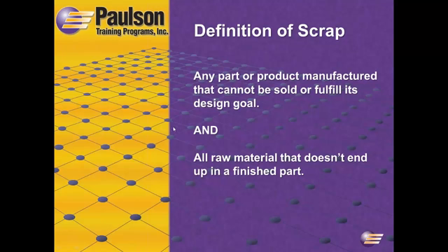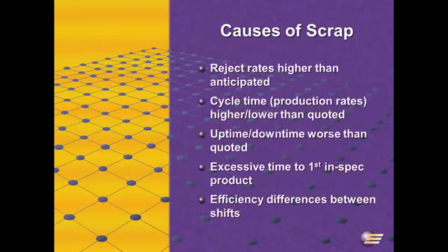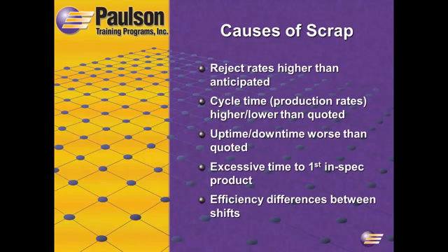It's really the root between profitability and unprofitability. Now, sometimes we can regrind our scrap and sometimes we can't. Depending on the process, obviously, most of the time we can, unless we're in certain industries, as we know, where virgin material is required. When we can, that's good, except that we have to go find that bad part, and they usually don't come in ones. Identify it, grind it, reuse it at a consistent rate, hopefully, and then obviously more important than any of that is to solve the problem to begin with.